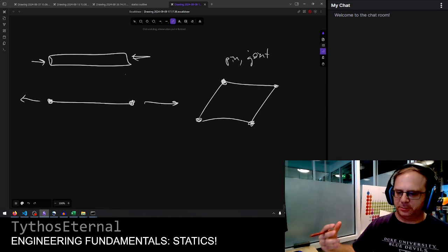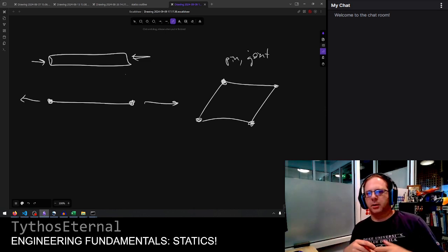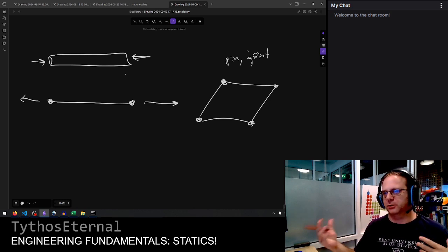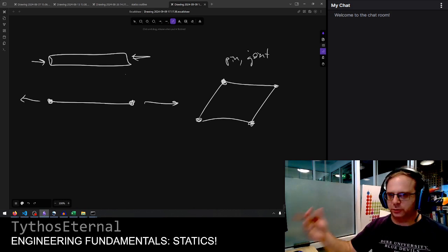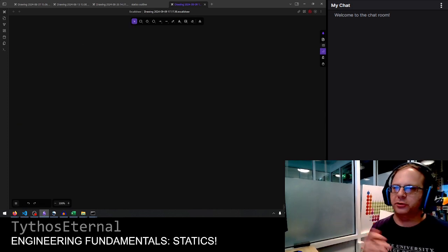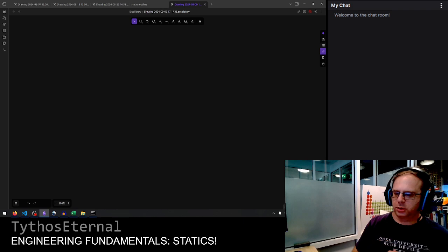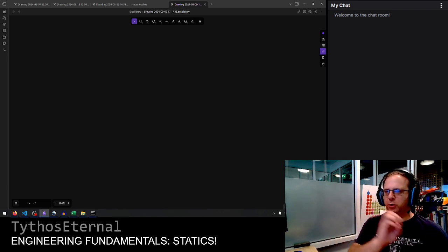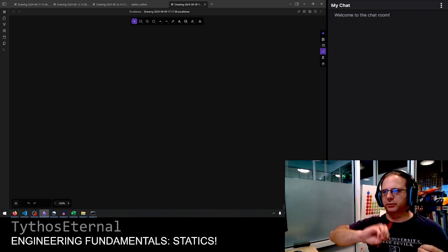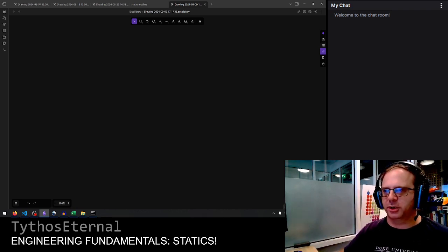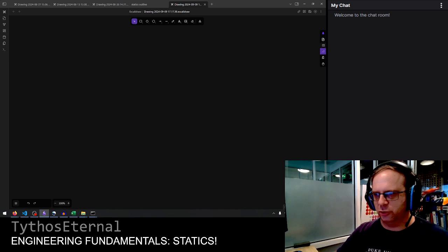And those joints represent places where these forces combine, places where we can add the forces, set them to zero across different components, and then determine, okay, given these relationships, what constraints help us figure out what the forces are. So those vertices of that graph are basically, as we go through a complex problem, those are the steps, going from places where we know more to places where we know less. We'll solve for the different variables and unknowns at each step, and then sometimes we'll combine them in ways where they might cancel out, or they help us figure out a set of simultaneous equations to solve.